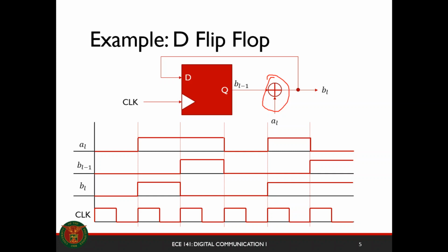In this modulation scheme, if the current input is 1, the output will transition into a different state. Initially it's at 0. Once we have an input of 1, your output transitions to 1. If you have another input 1, the output transitions to 0. And once the input is 0, your output does not transition at all. We call this the NRZI signaling scheme. This is a baseband signaling scheme, a class of non-return to zero signaling that has memory, specifically a memory of 1.